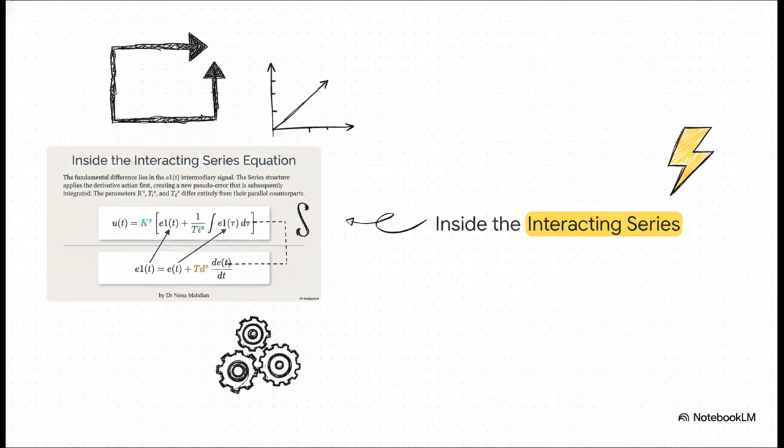Looking inside the interacting series equation, the fundamental difference really lies in that intermediary signal, E1 of t. The series structure applies the derivative action first, creating a sort of new pseudo-error that is subsequently integrated. The parameters here, k superscript s, t sub I superscript s, and t sub d superscript s, differ entirely from their parallel counterparts. The output equation, u of t, equals k superscript s multiplied by the sum of E1 of t and 1 over t sub I superscript s times the integral of E1 of tau d tau. This crucial pseudo-error E1 of t is simply the original error E of t plus t sub d superscript s times the derivative of E of t.